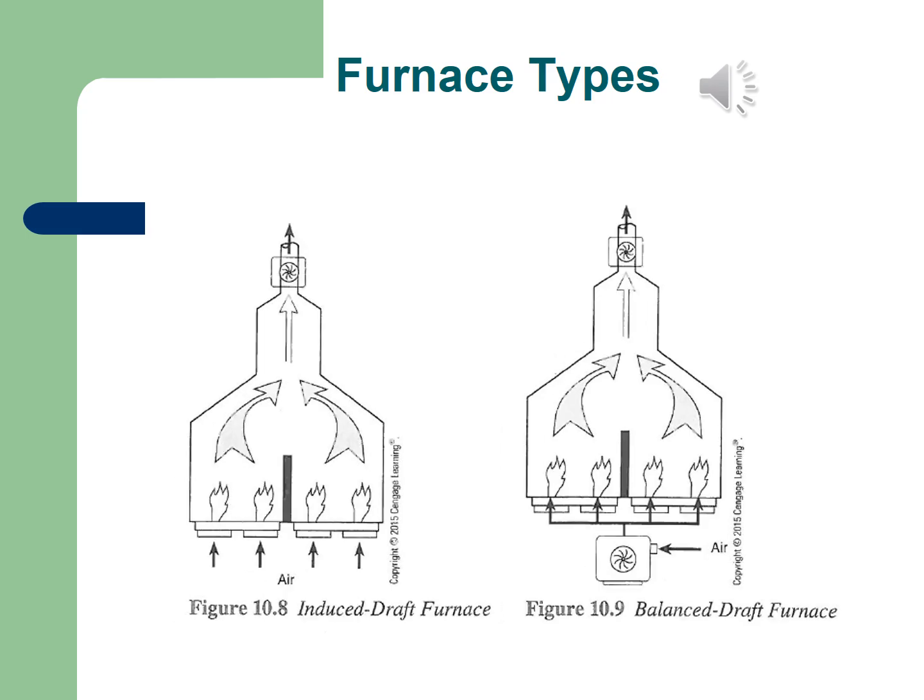As said on the previous slide, on figure 10.8, we can see an induced draft furnace. Here you can see that the fan is placed at the stack. So that means it's basically again causing flow from a higher pressure to a lower pressure, and this causes the flow through this furnace, so that you have a proper, I could say, heat exchange of this heated air that flows across the tubes.